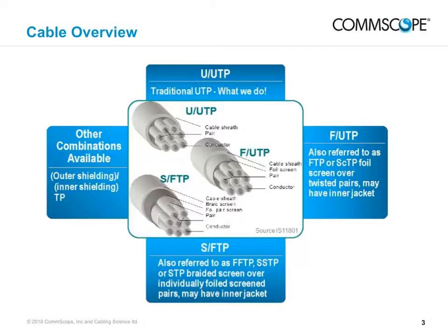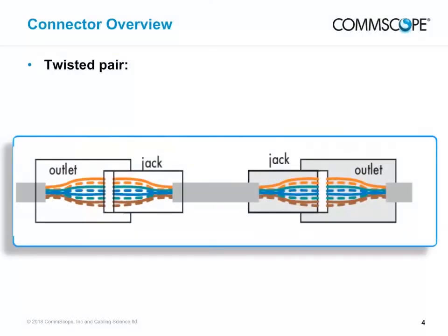Like the foil in FTP, the shield is designed to prevent electromagnetic interference from distorting signals in the cable's central conductors. The foil and shielding are intended to give extra protection from interference above that given by the error cancellation effect of the twisted pair itself. The twist of the pairs in high-performance twisted pair cables must be maintained during termination. All connectorization techniques require that the twist be maintained up to the point where the individual wires enter the connector or a piece of equipment.